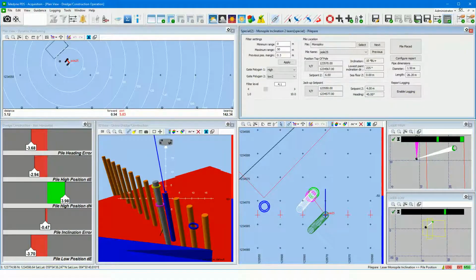If all these properties are set correctly, then the laser will detect the calibration object. This is indicated by the purple colored beams. Press on the calibration symbol to calibrate the laser heading. The heading correction value is automatically applied to the driver properties and the laser data is corrected accordingly.